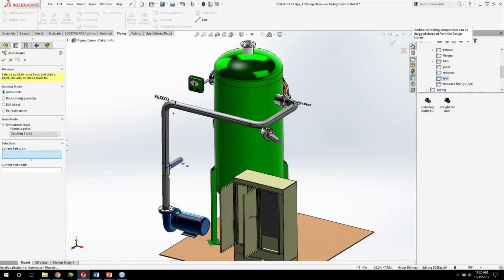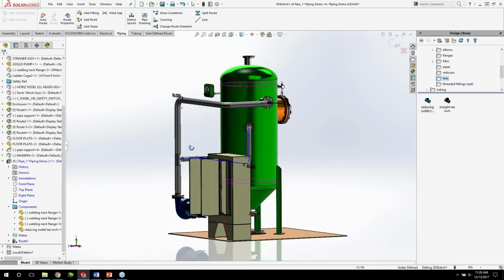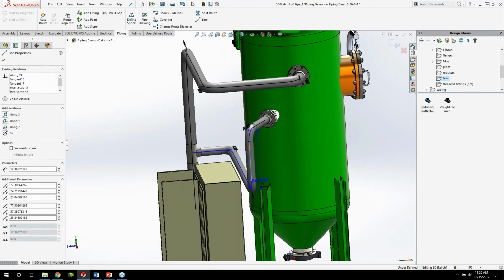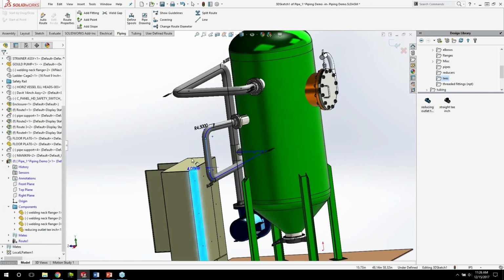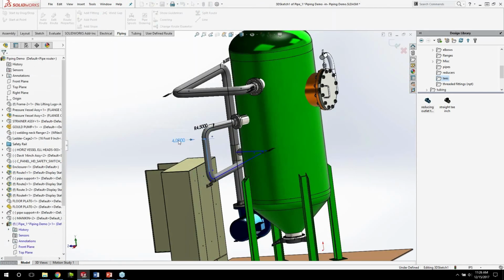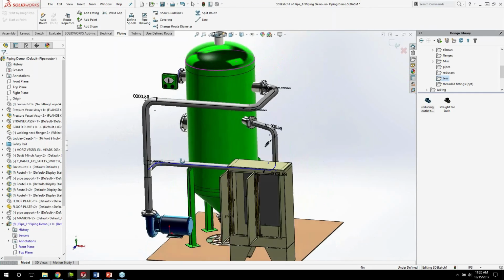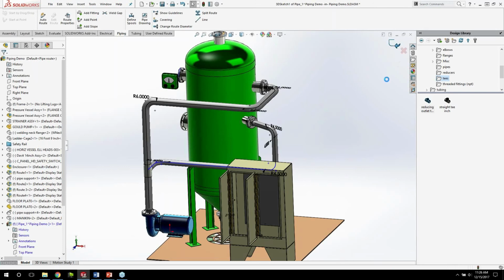And we can go here and say AutoRoute. Say OK. Right. Under Define 3D Sketch, you can go ahead and add these dimensions here as well, and create this here very quickly. Right, we'll say 4 inches. Exit sketch, and there's your pipe spool.